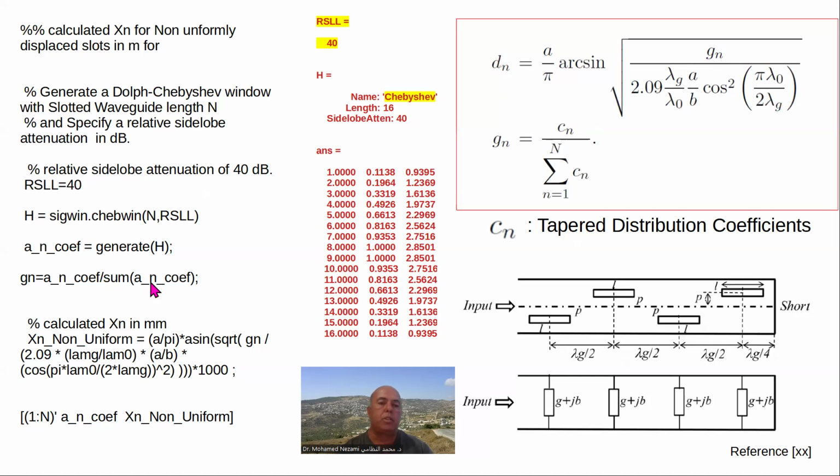So when you solve this, you get basically 16 coefficients that are basically mirror images. Half of them, 8 of them, are equal to the other half. So we've got 8 of them here and 8 of them here, and that's because the windowing function is symmetrical on both sides.